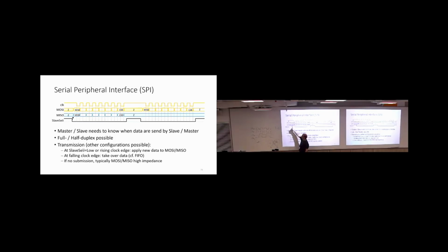So this here effectively triggers any action who wants to send, and this action needs to put data. And this time we start with the MSB as per specification. We start sending data effectively with the falling edge. We latch whatever is on the bus. With the rising edge, we set up the data. And this way, with 8 clock cycles, we can write 8-bit. And then we put up the clock again.